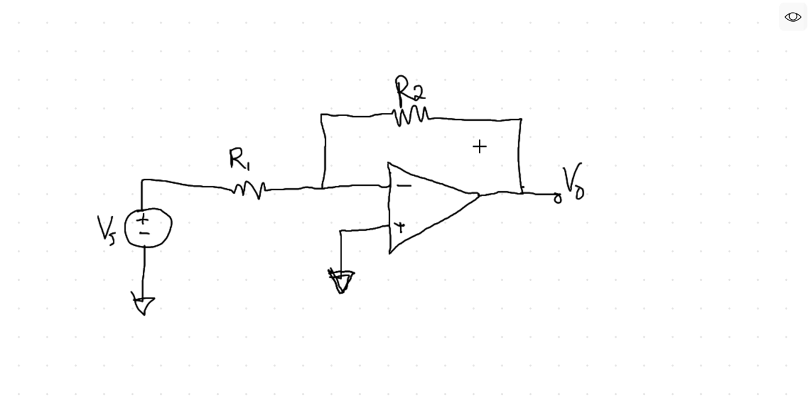So here's a typical op amp stage. Here's our op amp again, the triangle. There are two inputs: a negative input right here and a positive input, and that should look more like a positive sign with my ugly circuit. The positive input is connected straight to ground. The negative input has all this circuitry attached.